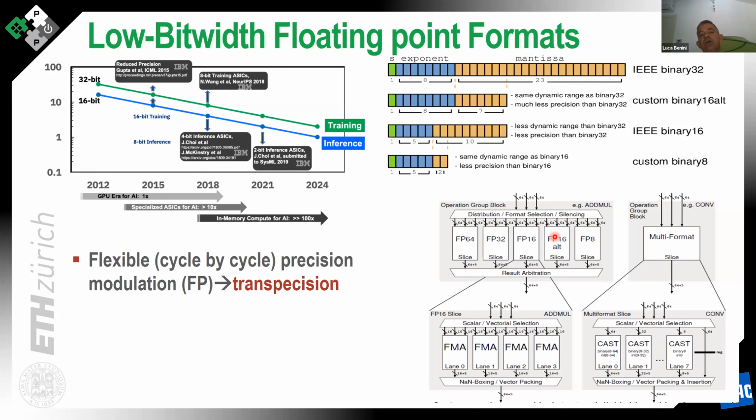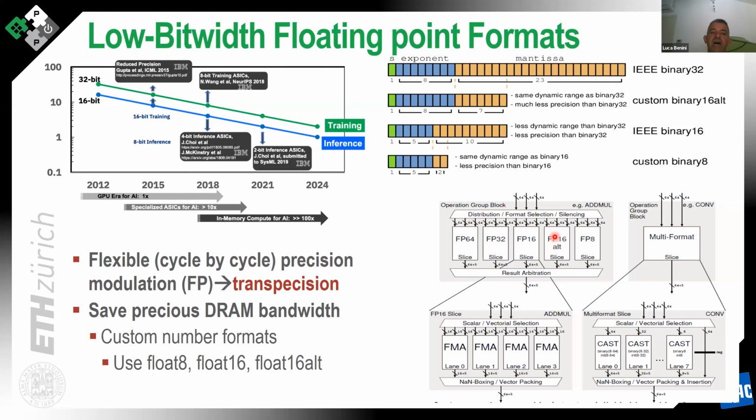If you play with this, you bring your energy per operation down very significantly, since you are getting with a single instruction many more operations done on smaller bit widths. So using SIMD mode, trans-precision, and tuning the precision is a way to get more useful work done in a single instruction, and so get your operation energy lower, thanks to lower bit width and SIMD mode.